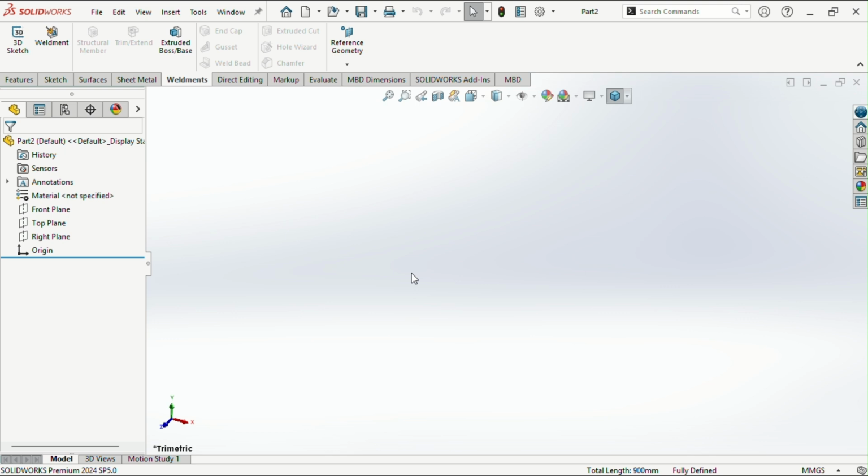It should carry the belt load, maintain the alignment, handle the vibrations, and provide the mounting support for the bearings and motor assemblies. A poor frame design can create belt misalignment, vibration issues, structural bending, and maintenance problems. So many things are related to the frame design. Always think practically while designing structures. Now let's start modeling.